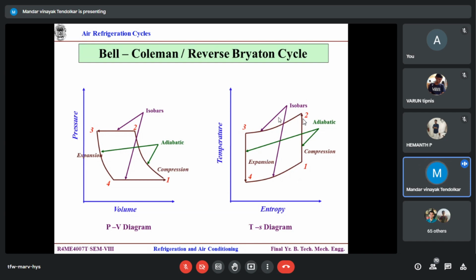And the same is applicable over here in the PV diagram. PV chart also, 1, then compression. So naturally volume reduces, pressure increases. Correct? So this is 2. And state 2 to 3, pressure is constant. It is only that the temperature is getting reduced. Obviously, pressure constant, temperature reduced means volume reduced. So that is why 2 to 3.